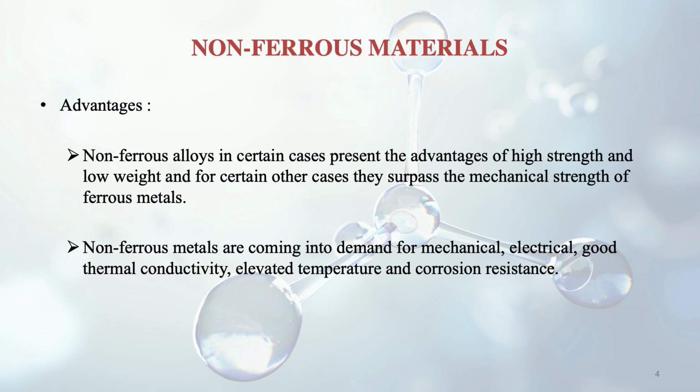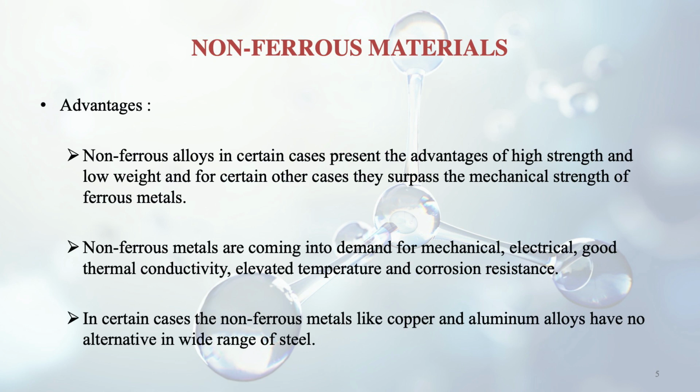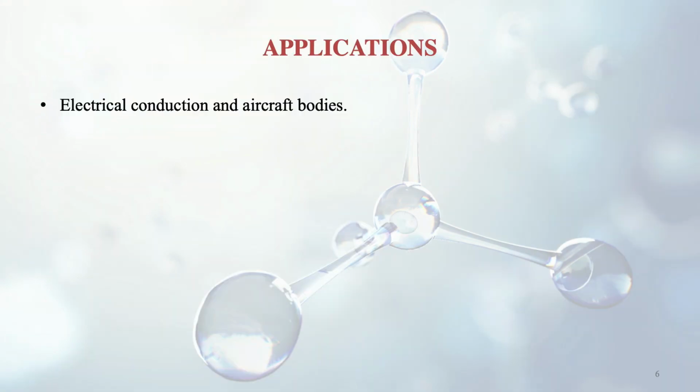You can see that they can even surpass the strength of ferrous metals, and these non-ferrous metals are coming into demand nowadays because of good mechanical and electrical properties, good thermal conductivity, and elevated temperature and corrosion resistance also. In certain cases, non-ferrous metals like copper and aluminium alloys have no alternative in a wide range of steel. What are the applications of these? These are very good for electrical conduction and aircraft bodies also.